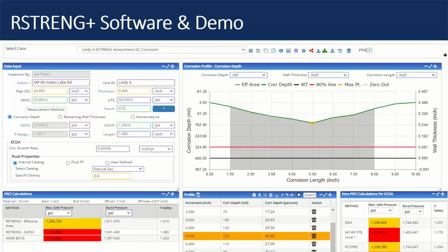We're just beginning to understand and determine the grade of pipe, because some of this is still unknown. And if you don't have it documented, you're going to have to default to 24,000 yield. So there's a lot of unknown metallurgy. There's a lot of unknown cracking that occurs due to secondary stresses and things of this nature. Do we really know our pipeline like we should? That's the question you have to ask yourself. If you do, I think P-square would probably work very well.